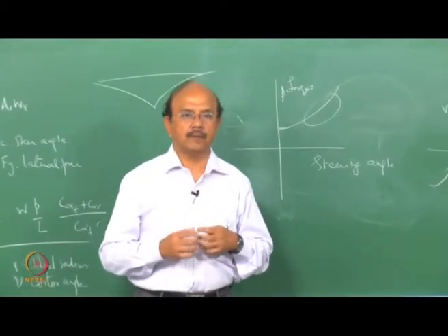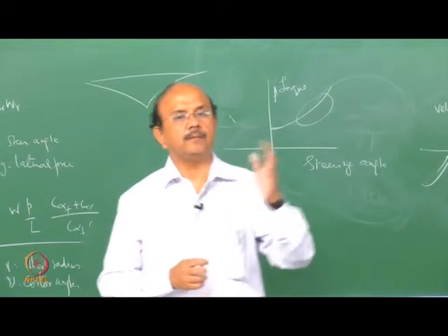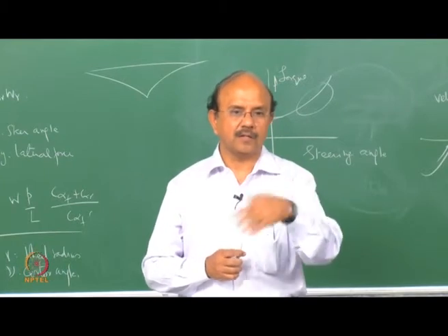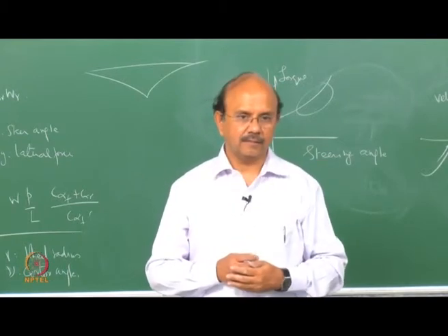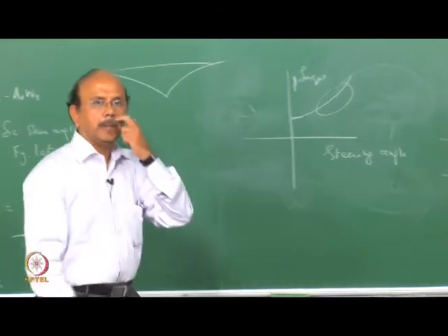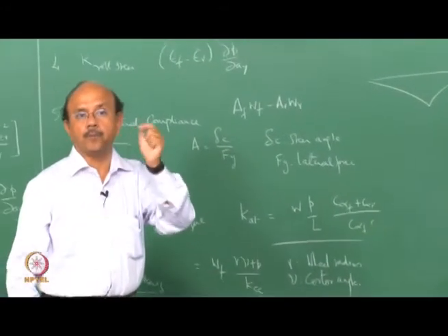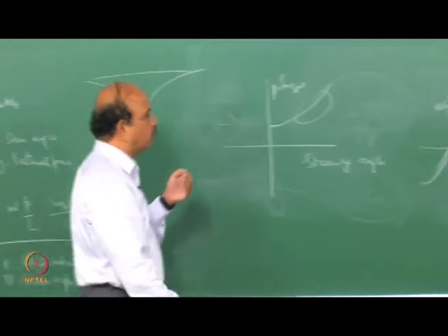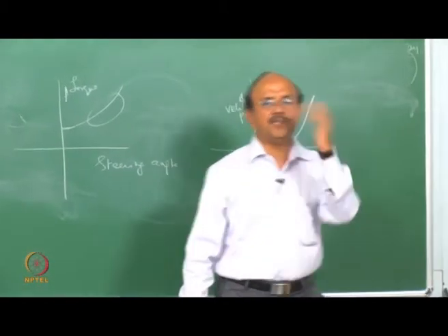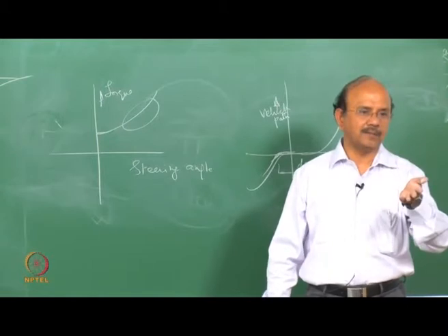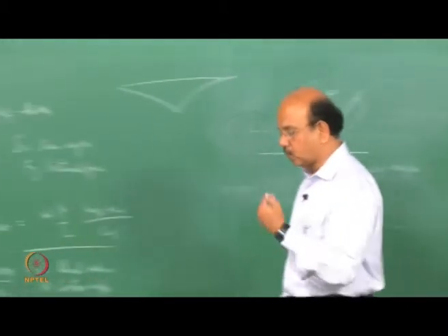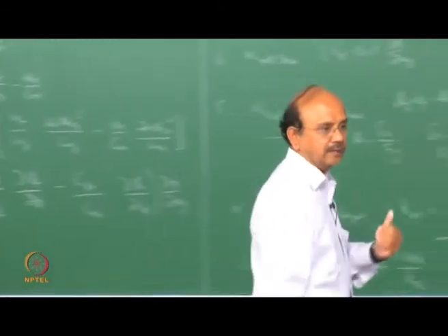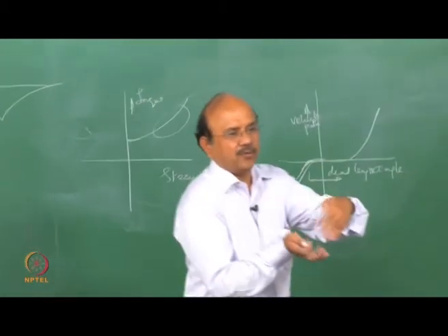So when you're plotting the vehicle path, what does it actually mean over here? The path is usually measured by the nose angle to your path. How much is the nose angle different from the path you want to take? Deviations. That's it. You can plot the deviation as an angle of the nose angle. As I told you, when I say there is a path and deviation from the path, we talk about the nose angle. Even when you look at the understeer or oversteer characteristics of the car, we look at nose angle. Nose angle is simply the attitude of the car.